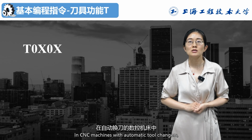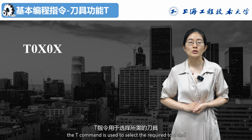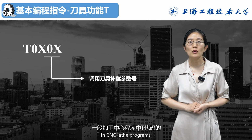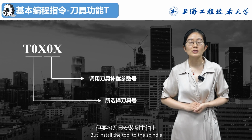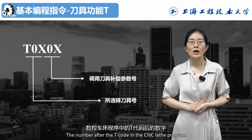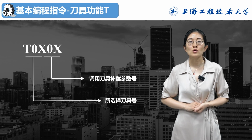In CNC machines with automatic tool changers, the T command is used to select the required tool and sometimes specify the tool compensation number. In CNC lathe programs, the number following the T code, for example, T10 means selecting tool number 10, but does not install the tool to the spindle. You must write the tool change command M06 to achieve the tool change action. The number after the T code in the CNC lathe program includes both the selected tool number and the tool compensation number. For example,